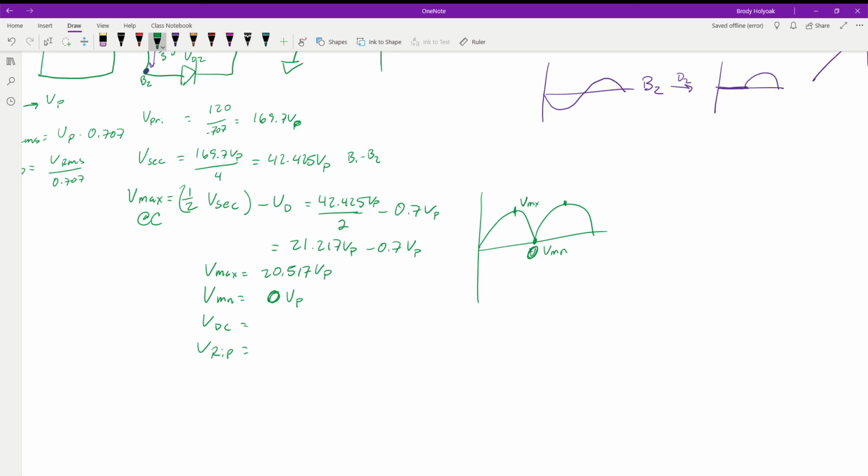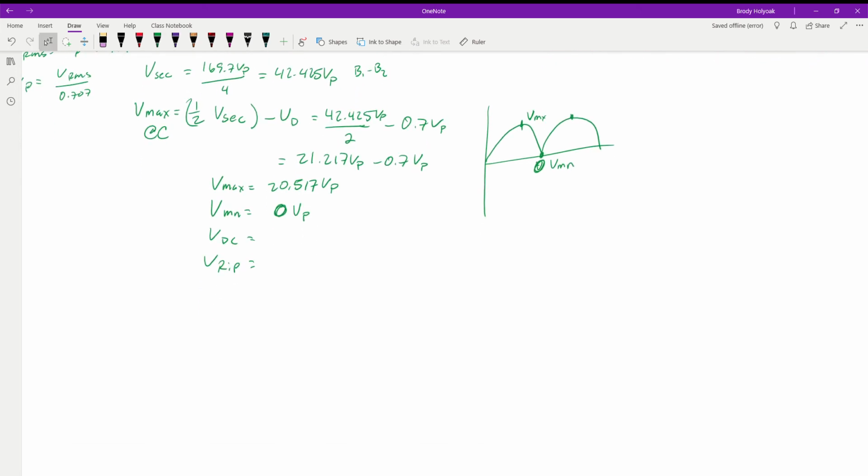Not necessarily a problem, but we have to use different calculations. Same ones as we used before; we'll have a different set when we get into filters. So again, when we come into the circuit, we need to solve for what the values are. Our VDC, remember, since it's an unfiltered circuit, is equal to the voltage max times 0.637 to give us the average, which is what our DC value is, divided by 2. Except, let's take a step back and look at what we have this time.